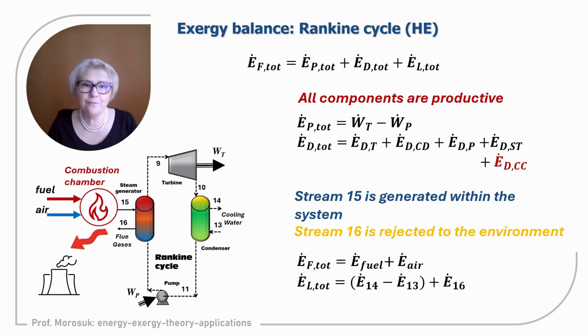But the same approaches we cannot use for energy analysis. Energy analysis is always energy in, energy out. But for exergy analysis, we can properly discuss exergy losses as inefficiencies within the system, but simultaneously with a proper definition of fuel of the system.